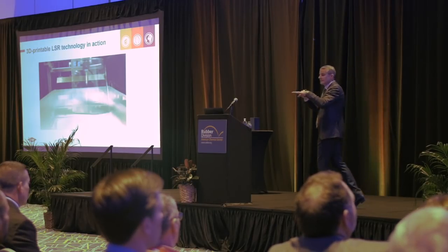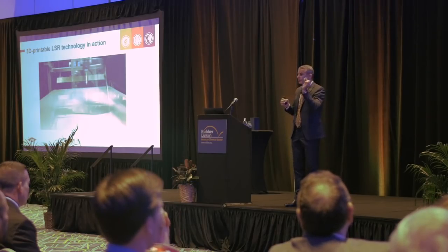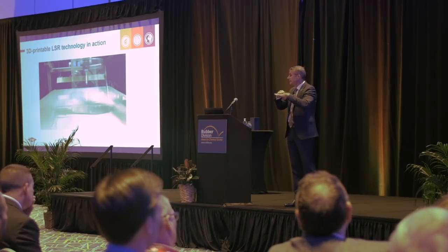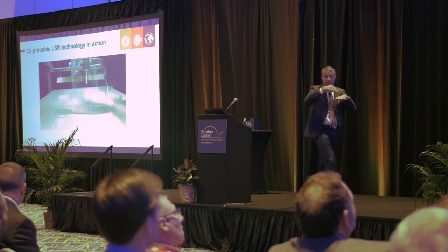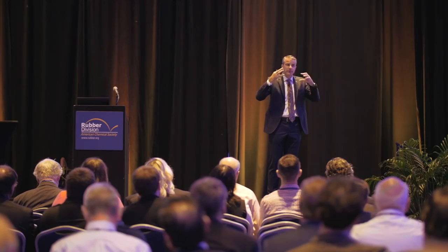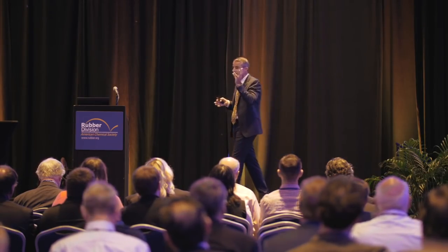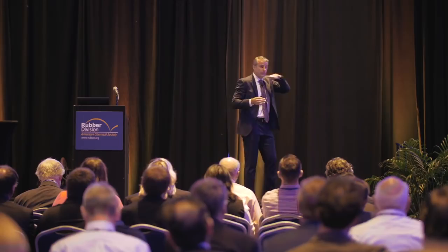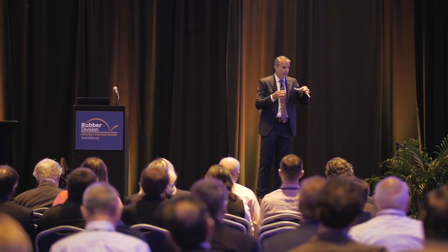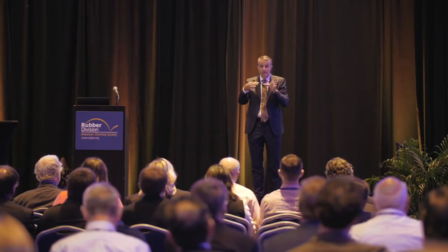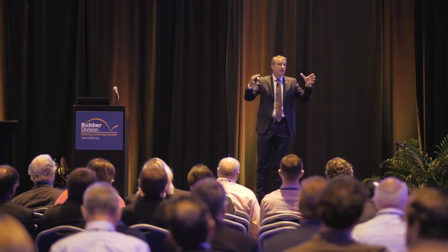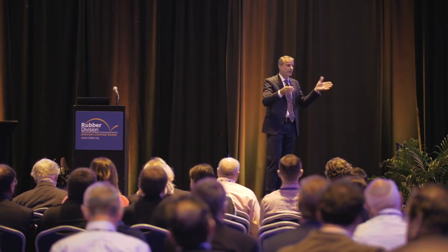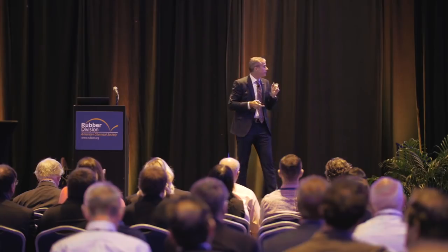But think about the technology. So it has to cure fast. It has to have enough adhesion instantaneously. And it has to interlock with the previous layer that just has been cured, right? So when you think about the molecular design, it's not that easy anymore. Now on the equipment side, those guys have to bring this cure cycle in there. They have to make sure that if you have this infrared, that it really covers every part of every side and every portion of that part equally, because you need to have full cure. And so it just gives you a sense of what you can do.